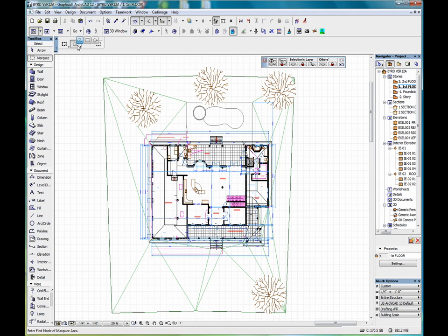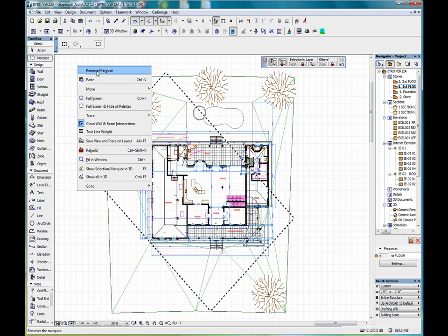We also have, as in other tools, our rectangle and our rotated rectangle. Draw a rotated rectangle. We click our start and end point and then draw out our rectangle to the required length, and click one more time, and that defines our rotated rectangle. We'll remove that.